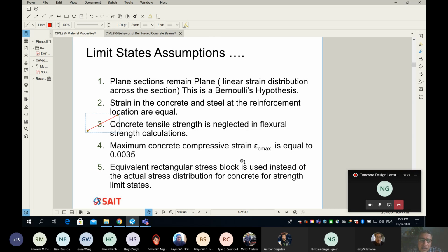Number two, the strain in the concrete before the failure, which we talked about last class, I guess. It is epsilon, not E, epsilon, which is a strain, and then sub c max. C is for concrete, and max means maximum before concrete fails. I'm referring to this name here: epsilon c max.